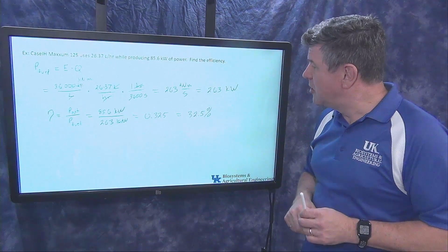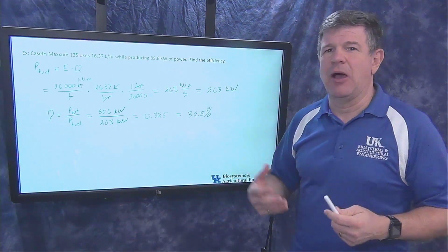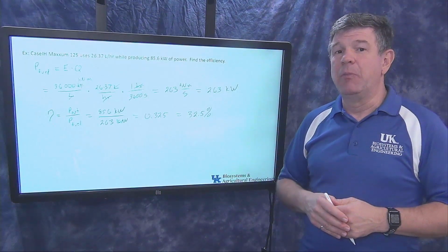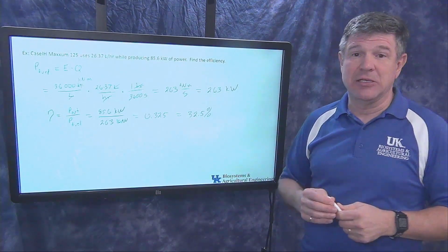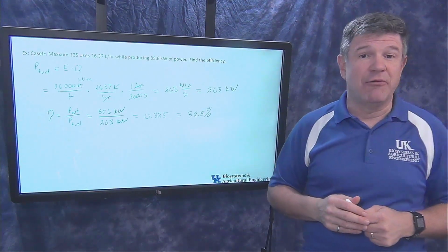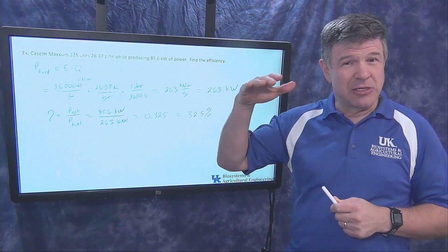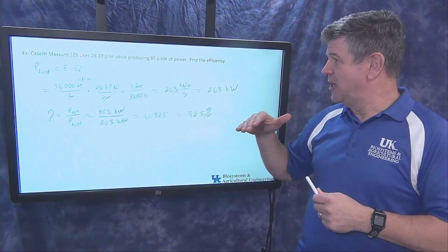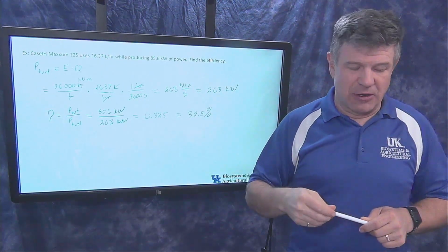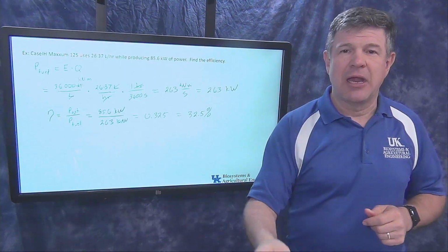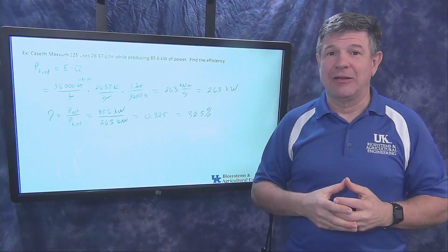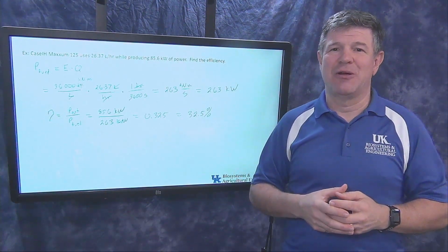This one's 32%. And actually, depending on the operating point that you choose for the tractor, it might go a little bit higher. But in general, what you find is internal combustion engine efficiencies are not going to go above 40%. That's about our ceiling. So you're never going to see more than about 40% of your fuel power actually converted into mechanical useful power. Okay, so realizing that, shock factor, right? Wow, these things are inefficient.